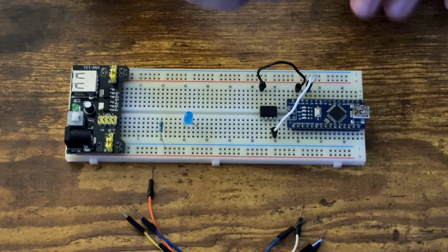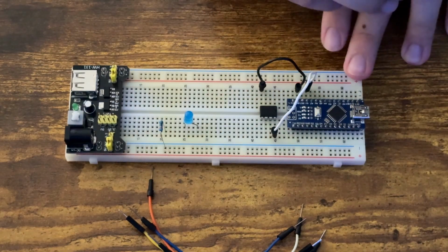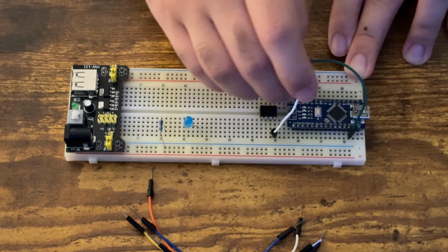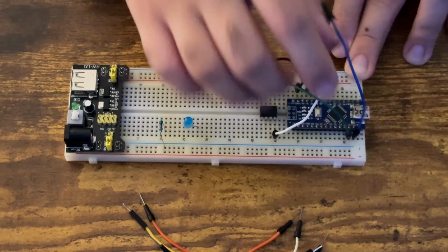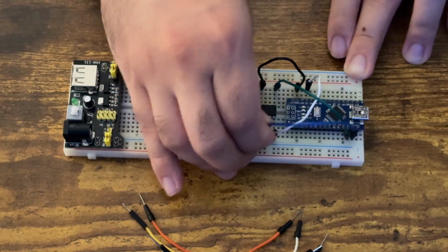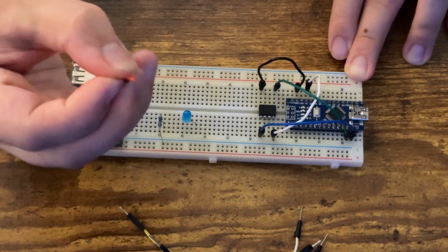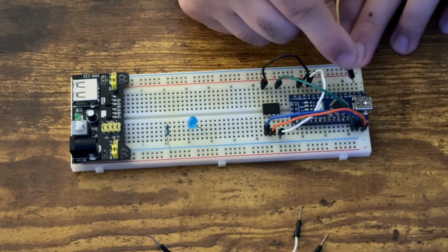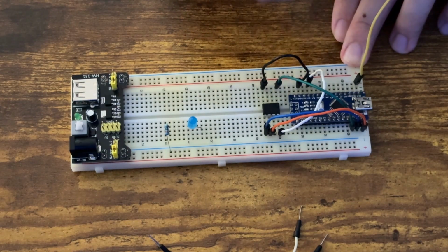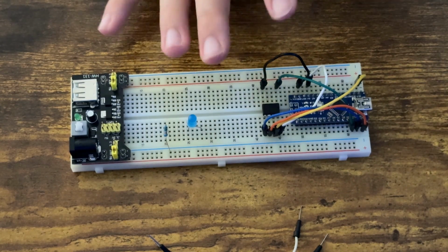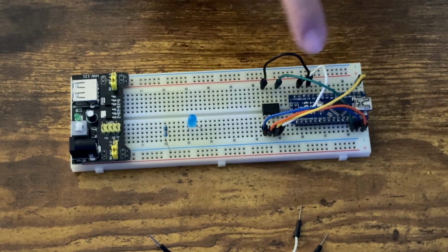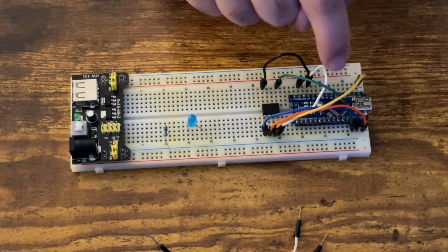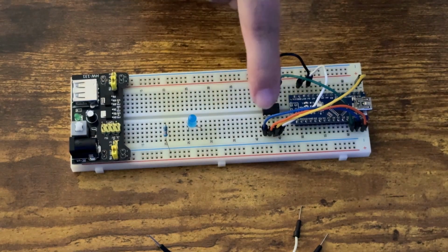Now, SPI lines. Arduino Nano D10 goes to ATtiny pin 1. Arduino D11 goes to pin 5, which is opposite to our ground pin, pin 4. D12 goes to pin 6. And the last one, D13, goes to pin 7. Okay, so now we connected, and Arduino will transfer all the binaries, the C code that we'll write, through these 4 wires.